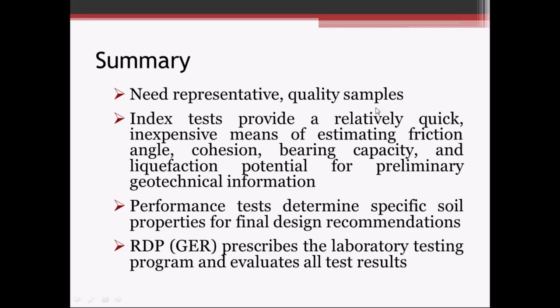Okay, and that brings us to the summary here. So just to summarize, we need to make sure we have representative quality samples, both from a collection standpoint and getting those to the laboratory. The index tests provide a relatively quick and inexpensive means of correlating engineering parameters such as friction angle, cohesion, bearing capacity, and liquefaction for preliminary geotech information.